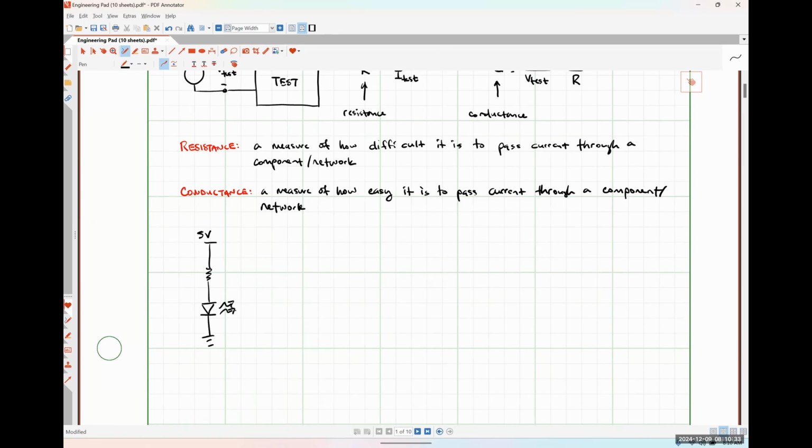with an LED, right? And if you didn't put that resistor in, which I'm sure some of you erroneously didn't put it in, what would happen? Your LED would shine really bright for a split second, and then it would never turn on again because it passed so much current through it that it burned out, okay? So we can talk about why it burned out in context of resistance as well. But our first application is, typically speaking, just limiting the amount of current that we can have flow through a particular element is a reason why we would use a resistance, okay?